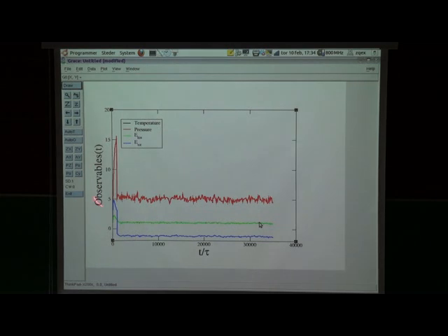So you can see I did the push-off at short times. I'm going to have very strange things happening, but then I equilibrate, and for the remaining part of the simulation the pressure is constant at 5. The kinetic energy is constant at 1, which it should be because I specified that in my simulation.